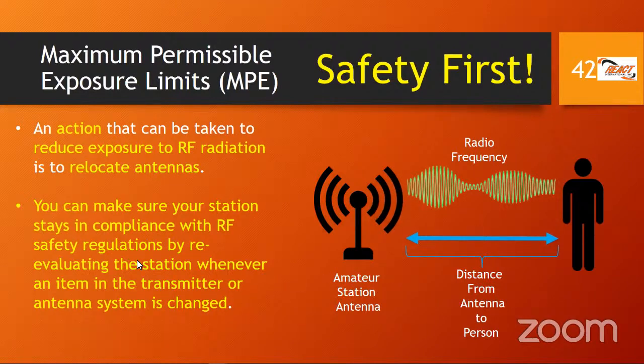If you were to do any of those things, change your transmitter or change the antenna, you need to reevaluate your MPE, or maximum permissible exposure. So any change that you make, reevaluate. And that's the point of this bullet point, an exam question.